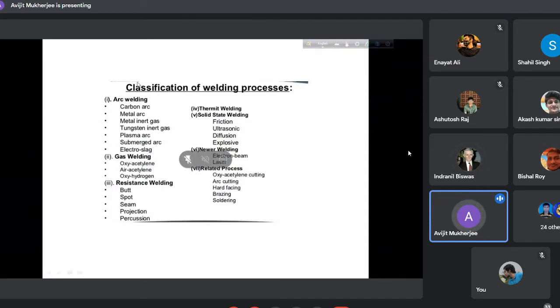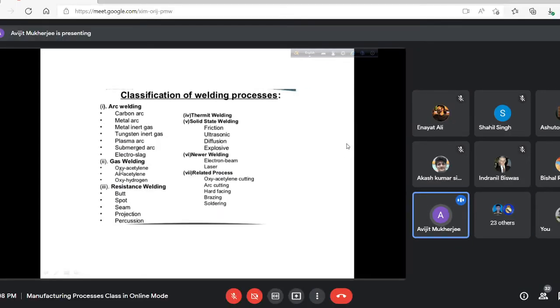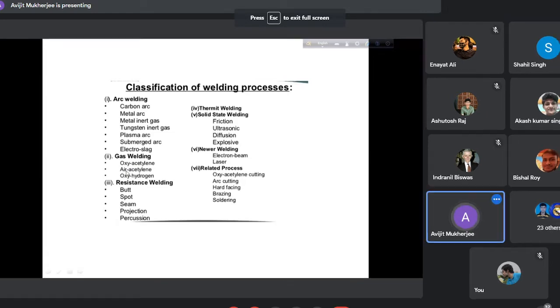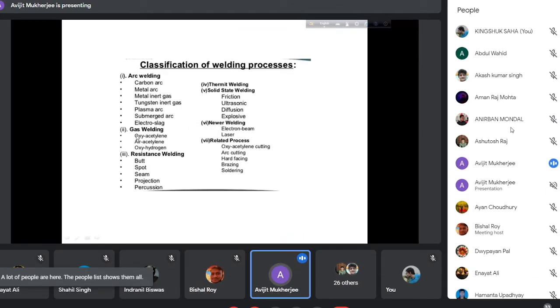Okay. So we had mentioned, not in a tabular form, but you just observe the arc welding. Previously we had discussed gas welding. What are the different techniques? Oxyacetylene, oxy-fuel. Oxygen with acetylene as the fuel, or oxygen with hydrogen as the fuel. Oxygen is a supporting gas, and oxygen supports combustion. If we don't have oxygen, air may also be used, but that is not a good quality. So this is the oxy-fuel welding.